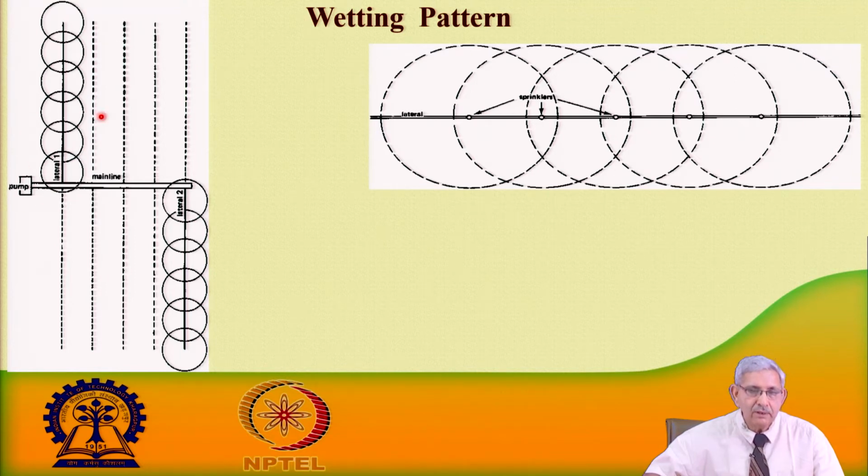So, when sprinkler is operating, it forms certain percentage of overlap. So, this is the typical water distribution pattern from a single sprinkler. Now, another sprinkler is kept at a certain spacing, let us say it is at 50% of the diameter of coverage. So, the wetting is formed by the second sprinkler. So, this is the common area.